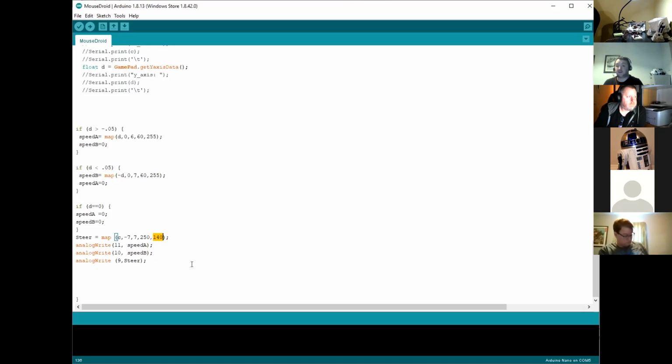Okay, and that's just connected up the exact same way. TX, RX, ground, and VCC. Yeah, the older HC05s and HC06s are a bit more finicky to get working. I found the HM10s to work a lot more reliably and simpler. Yep. Cool. No worries. Thank you. Any more questions while we're kicking around on that?